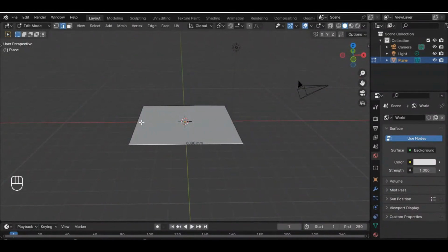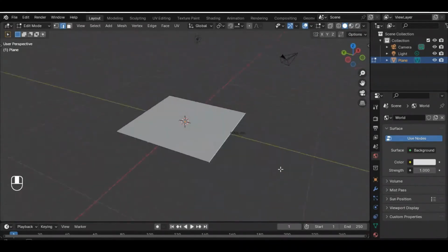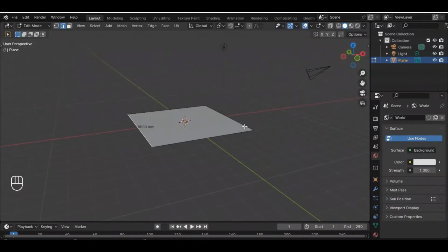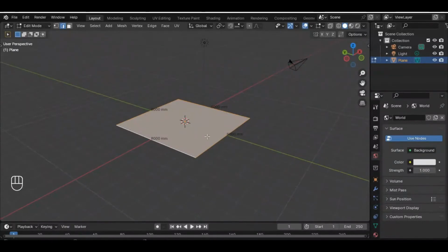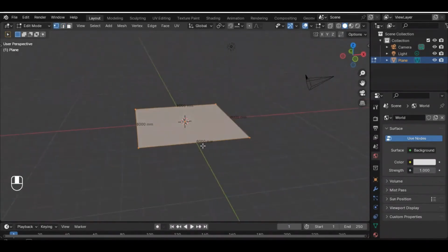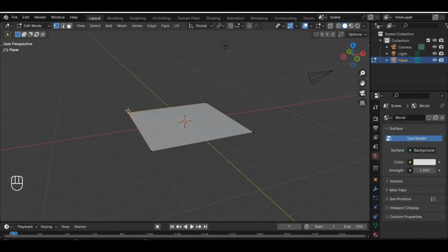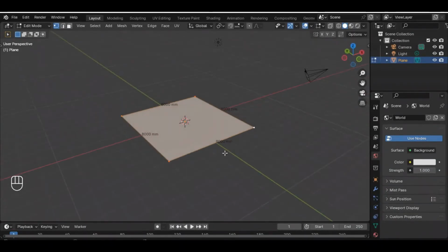So now, to be able to make this into something that looks like a house, you just need to click all the edges. You can just press A, like you're clicking the face. But what we need really is just these edges. You don't really need this face. So I can go to vertex select mode and then just click my vertices, even though it's still going to end up clicking the face, because it's actually a face. So I can now extrude.